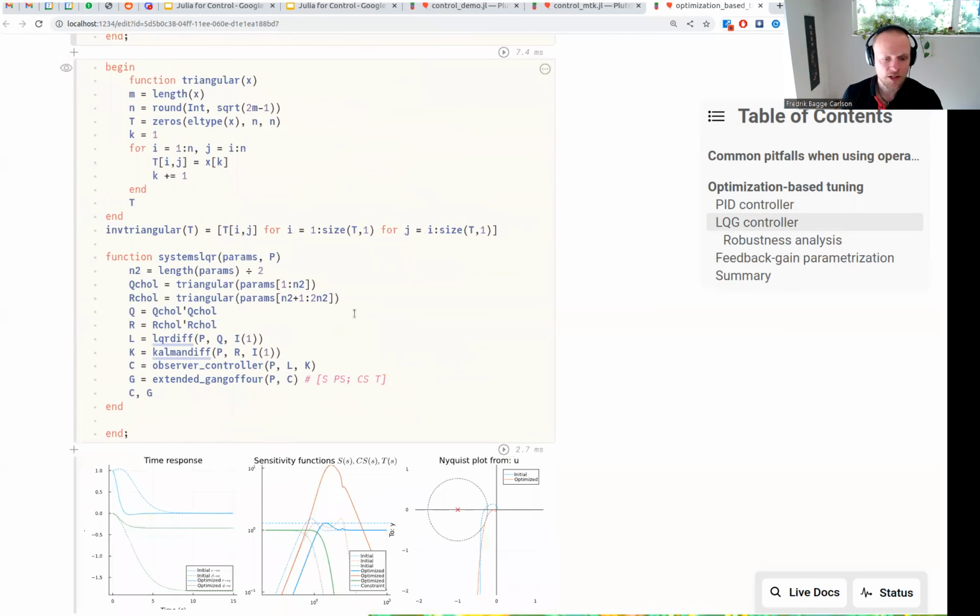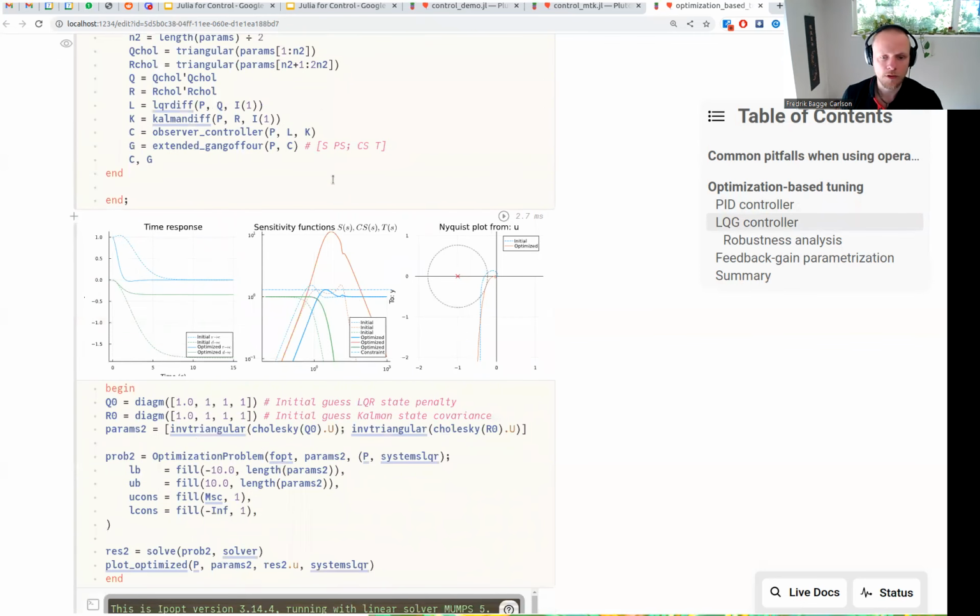And then when we actually solve this problem here, we're looking for the penalty matrices for the LQR cost function. We now obtain optimized penalty matrices. And this is an instance of inverse optimal control. So we are solving a problem to find a cost function. We are actually finding the parameters of the LQR cost function. So that's perhaps a bit different from your traditional optimal control